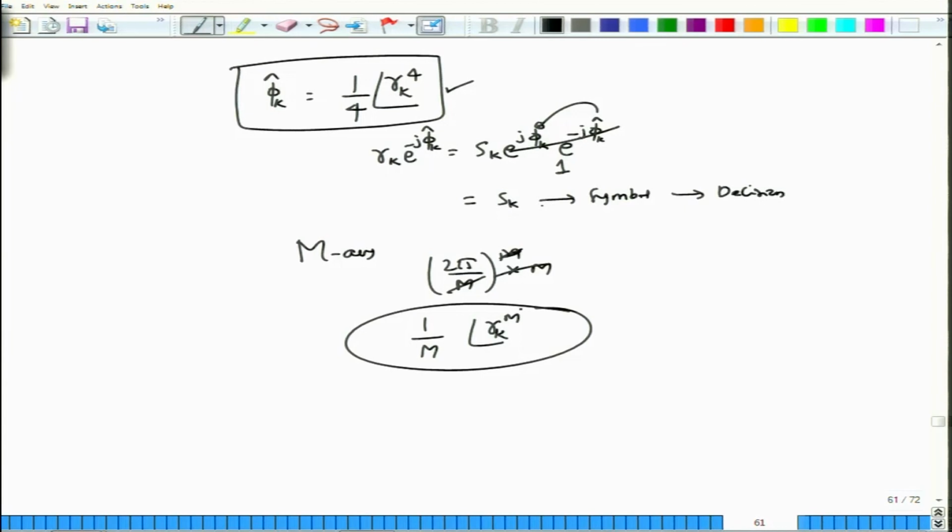In that case everything works out fine, but what do you do with noise? Well, noise is additive white Gaussian noise, so it has an equal probability of being positive and negative. So what you can do is average these symbols. Again, you can form a block: you have Rk, down to Rk minus L plus 1, an L-length block. Again, you don't need to know any of your transmitted sequence.